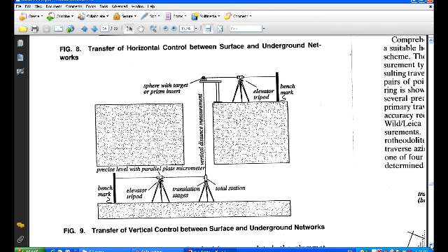So we have at the top of the shaft a bracket that holds this Taylor-Hobson sphere that has a target or a prism in it. There'd be two separate spheres, one with a prism like we would normally see in a retroreflector, and the other would have a target. They're both, as I said, manufactured to very high precision so that the target is effectively at the center of the sphere, and similarly with the reflector.